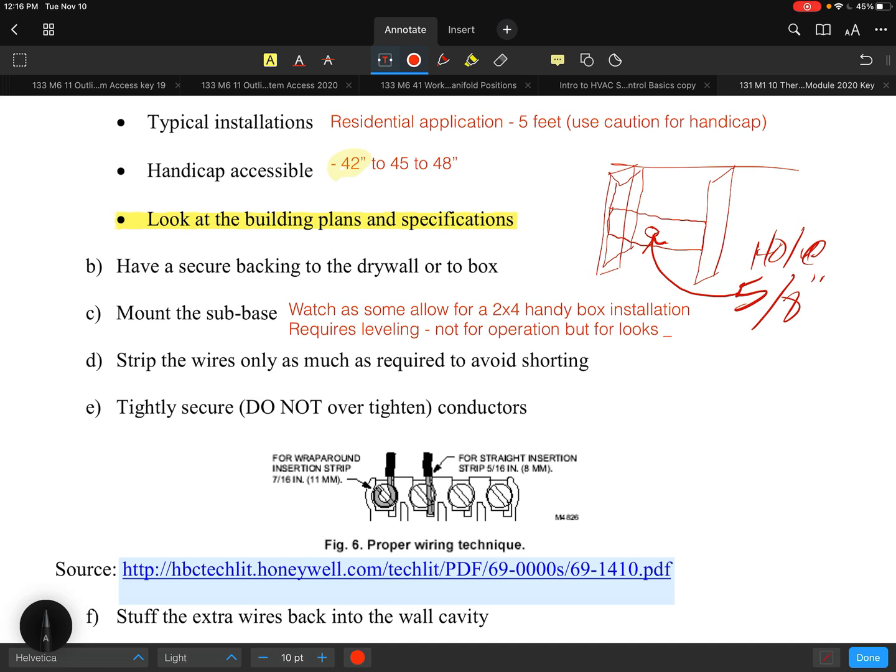sometimes people will tie a knot around the wire, but it always helps to take some pictures or make a note of it, because it's happened multiple times where a technician would stub a wire out of the wall, and the drywaller never sees it. Sometimes they don't care, depending on who you've got working on the job site. But you have to be aware of that. Sometimes it helps to make sure you've got images and pictures and things like that.